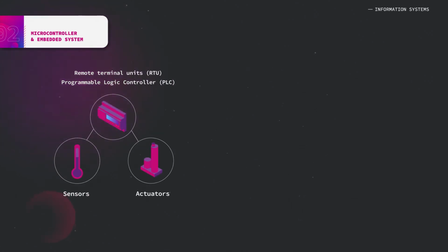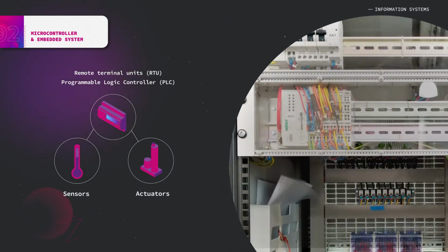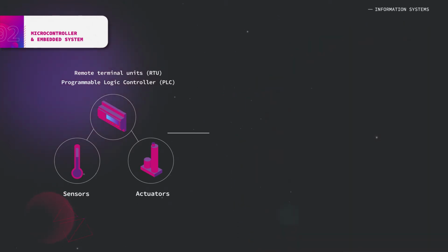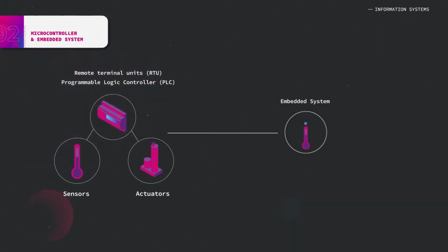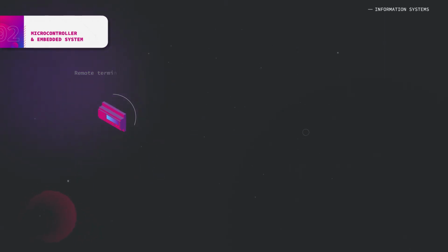Automation based on sensors and actuators connected to a programmable logic controller requires setting up an electrical cabinet. In this cabinet, the PLC is here. One of the current trends is to embed controllers with sensors or actuators to facilitate access to unreachable places with wireless connection. These embedded devices are similar to computers, but depending on the type, form factor, and shape, they can be quite similar to a microprocessor. Let's check them further in detail.